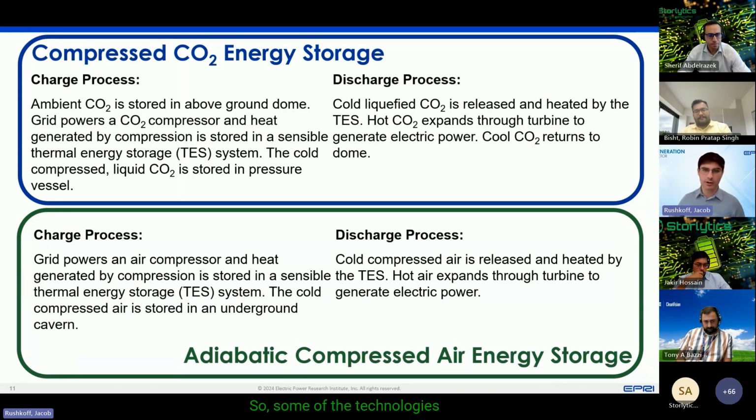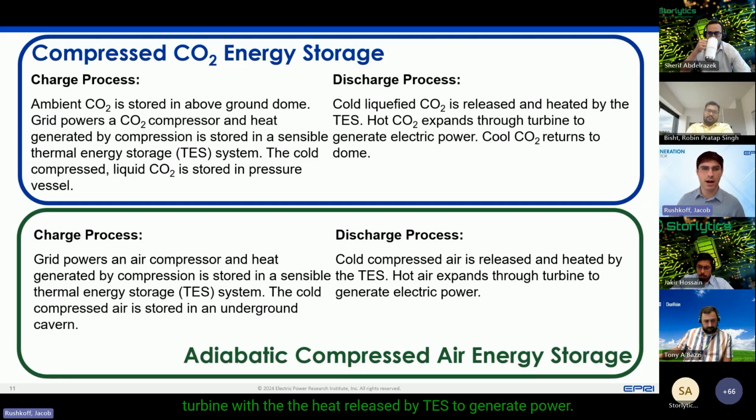So some of the technologies that we're investigating in this study as pairing with the lithium ion is considering compressed CO2 energy storage. This is similar to compressed air in the sense that you're storing liquid CO2 and the heat of compression, and then using the compressed CO2 in a turbine with the heat released by TES to generate power.